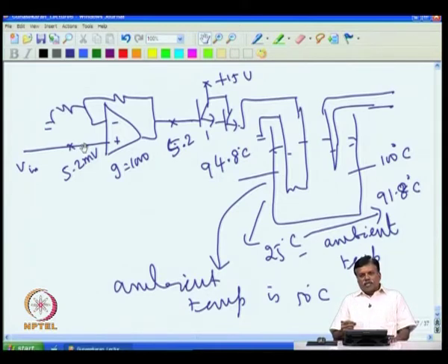If the temperature has to be constant throughout the day, then the only choice is you increase the gain, do not keep low gain, you go for high gain, but high gain will make the temperature go up and down. If you keep a low gain, then from morning to evening, if you watch the temperature of this, that will be changing slowly. So this is a serious problem, and this was recognized by the practicing engineers in the industry first,